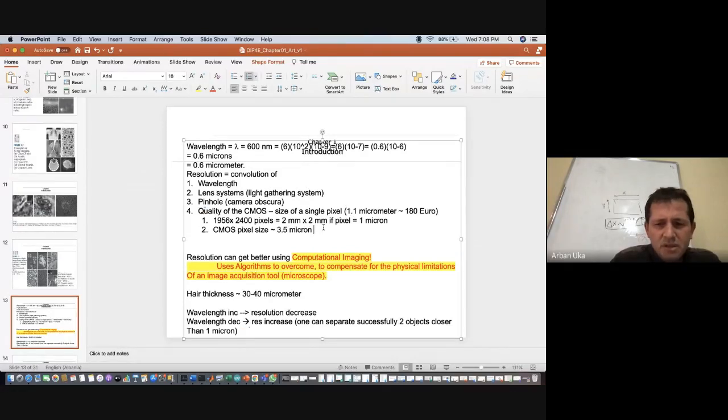It also has some other benefits, because you always have trade-offs: the signal to noise ratio is better. If you have a 1 micrometer pixel, the noise is higher. If you have a low contrast or low quality image, it might be best, depending on the application, to use a pixel which is larger. The 1.1 might seem better, but it's also very expensive. Sometimes, based on the trade-off that you have at hand, you might even go for a system like this.